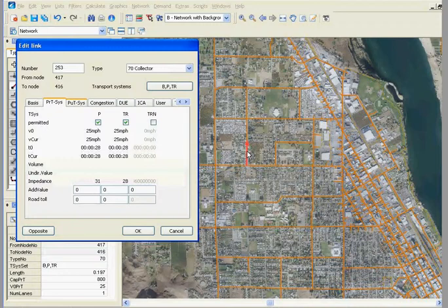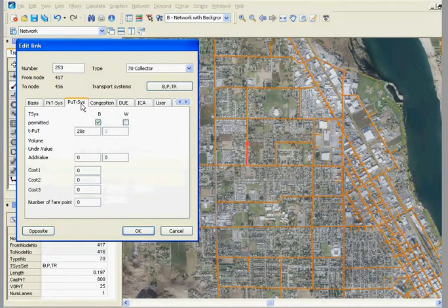Having public and private also enables the user to assign different speeds to the same network links. This is especially important in modeling public transport systems, such as bus rapid transit, where the bus may have a higher speed than cars running on the same road, or for usual bus service, where bus speed may be capped at a lower value compared to that of cars.